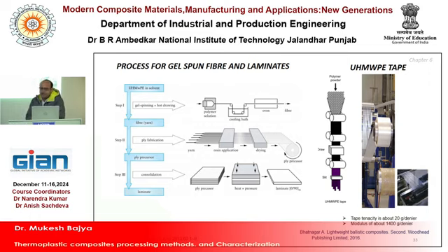So initially I discussed that we have prepared the polymer from powder directly to tape. In the gel spinning process, the imported material is manufactured from solvent or gel spinning, so you have to use the solvent, and this process is solvent free. Basically it's like a melt spinning process, but not exactly melt.